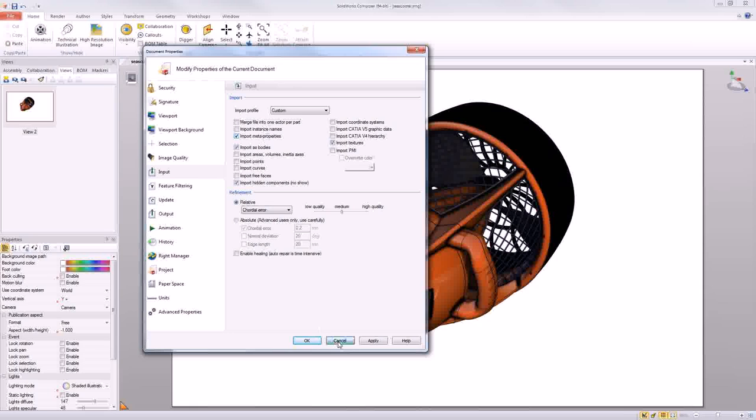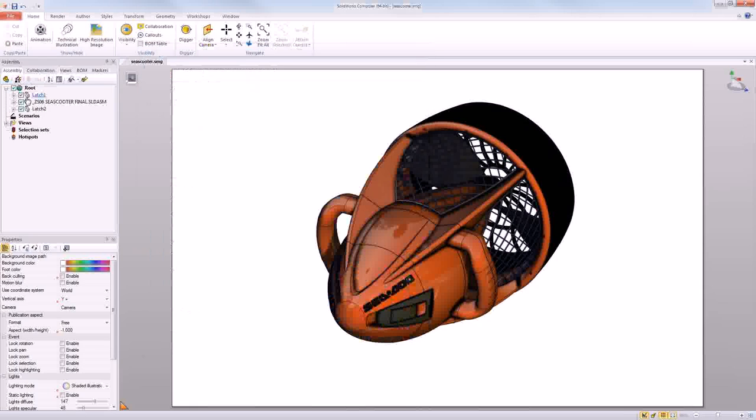So what you're essentially going to get is in your assembly tree over here, instead of seeing the file name showing up next to the component, you're actually going to see the body name next to the component. And that's how you know that you don't have that checkbox turned on. And for those individuals, I unfortunately had to tell them, hey, you're going to have to start all over again.